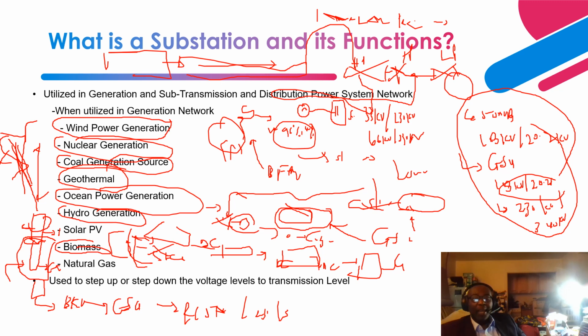Then from there, it goes back to the low pressure section, right? Then it impinges on the blades of the low pressure section. The blades in the low pressure section are much larger than in the high pressure section. So as you traverse from the high pressure section to the intermediate pressure section to the low pressure section of the turbine, the blades get bigger.